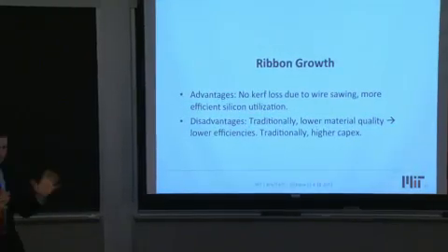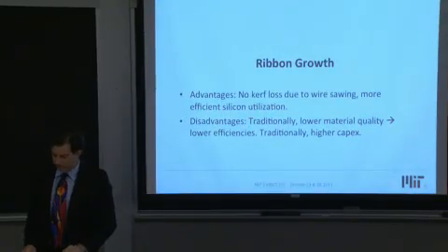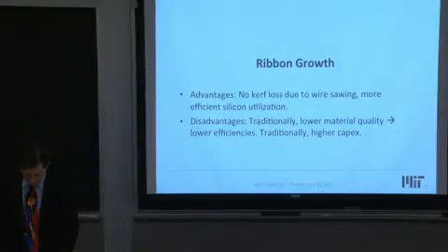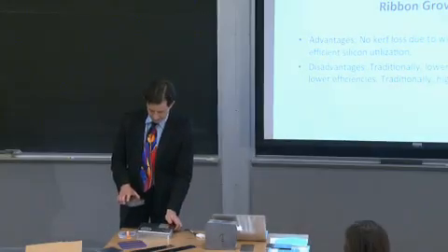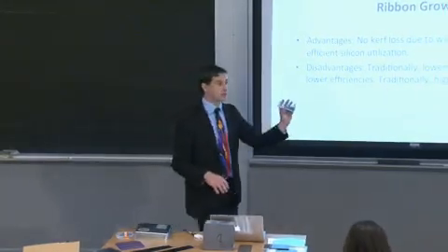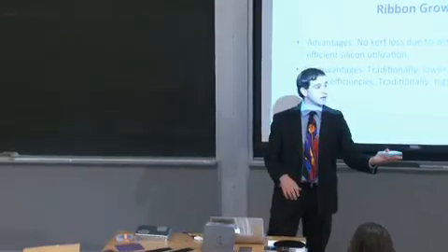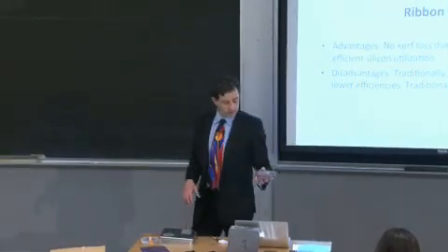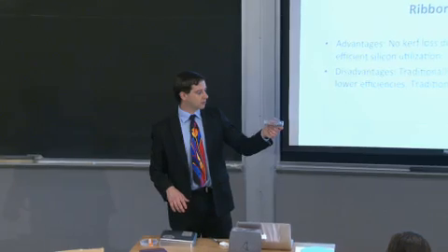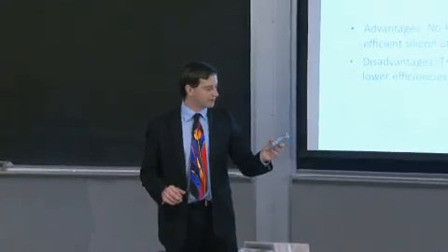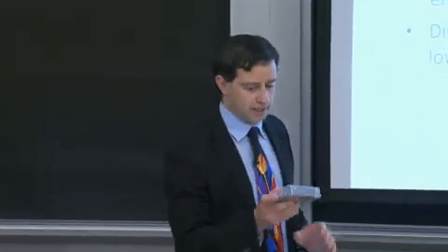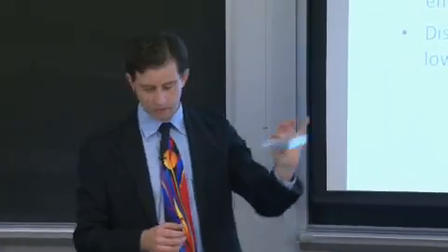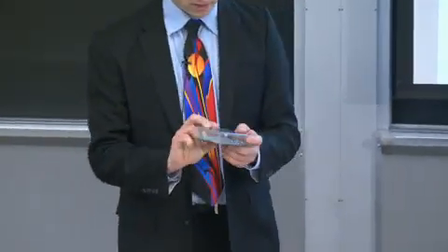And what we've done, just to resituate ourselves, we talked about the silicon feedstock, right? So we chatted about how you go from quartz in the ground and the carbon-bearing feedstock material to the heavily purified silicon feedstock material. This right here is probably on the order of somewhere between 8, 9, or 10 nines pure, very, very pure material. This Siemens grade polysilicon right here in my hand. And you've taken a look at this during last class, so you have a sense of what it is up close and personal.